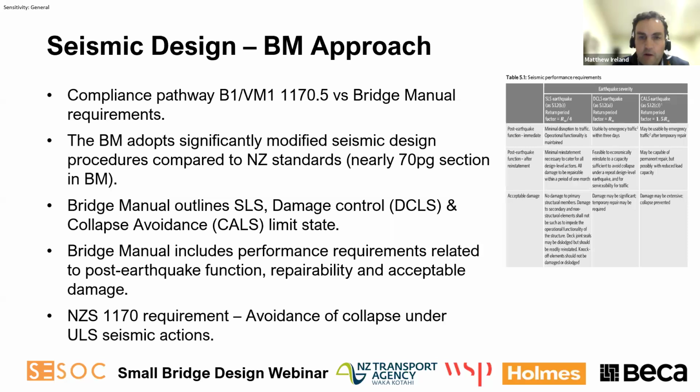So now just to briefly go over seismic design. Again, it depends on which compliance pathway you choose, but what we're just trying to highlight here is that the bridge manual adopts significantly modified seismic design procedures compared to New Zealand standards. If you look at chapter 5 of the bridge manual, it's nearly a 70-page section, so there's actually a lot of information in there. But the fundamental difference really there is that the bridge manual includes a series of performance-related criteria related to post-earthquake function, repairability, and acceptable damage, which are required at the different limit states.